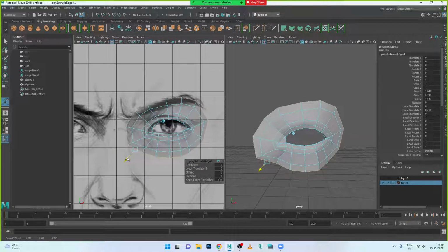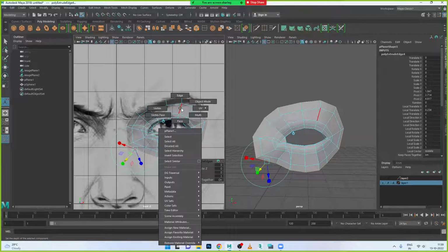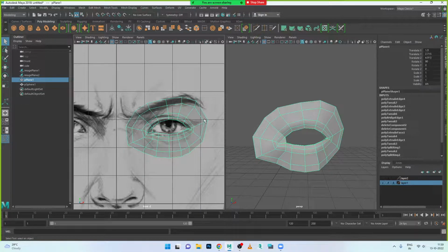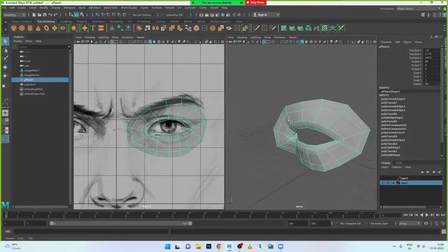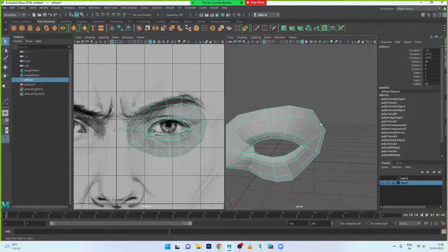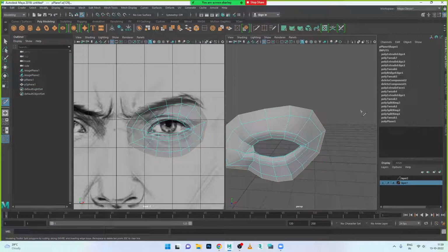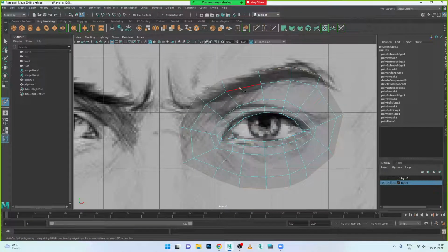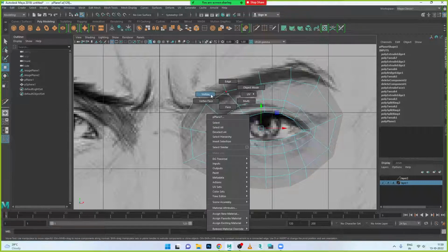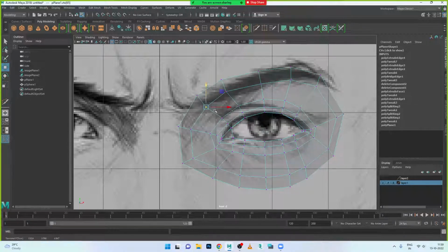Okay, here I need some depth in this now. Right click on this one, object mode. Where we need on this side now. So what you can do, you can add one complete loop, you can do that one, otherwise you can have multi-cut tool also. Okay, so again go to this front view, maximize this one now. From which area to which area you are having this depth now? From here to here we can say. Right now we have not adjusted vertex. First we'll adjust the vertex properly, then we'll go and we'll modify now.